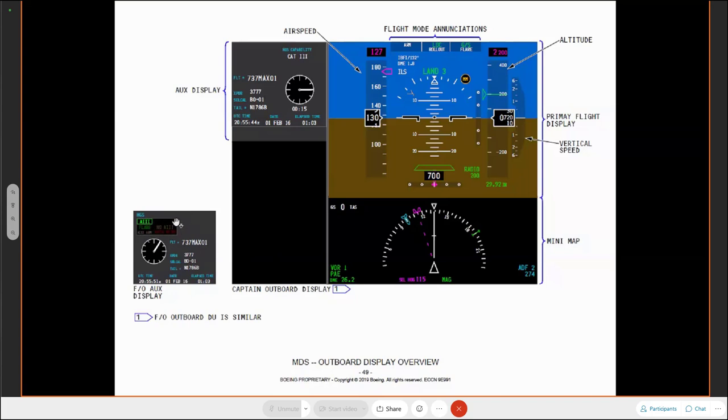It's just a graphic, in this portion here on the first officer's side. On there it shows the current capability of your head-up guidance system. The captain's flying using the head-up guidance displays, and the first officer is monitoring how capable that system is, any failures and suchlike. It's like a status and alert window. So that's the PFD.